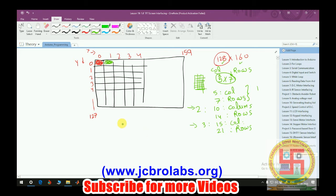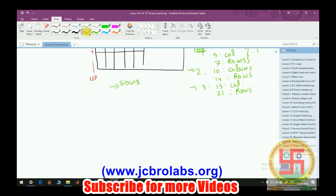One more thing: if we display a complete string, let's say JCBRO, then depending on the size, it will leave a gap of the corresponding pixels between two characters. If the size is 2, it will take 2 pixels between adjacent characters. If the size is 3, it will take 3 pixels.